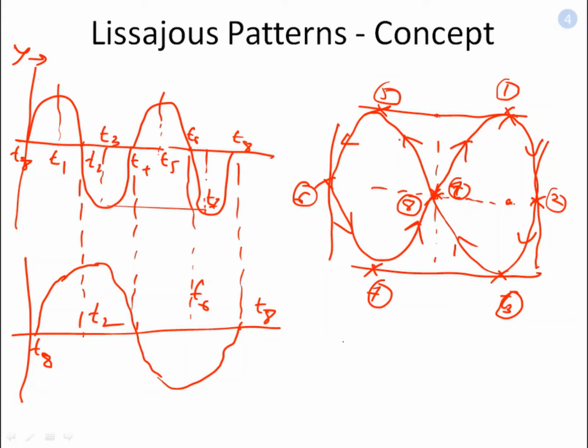So when we have to check the frequency Fy by Fx, Y plate is touched twice, while X plate is touched once. Either side, either you can take the top or bottom, or right or left, or you take the total number of touches. Y plate is touched 1, 2, 3, 4 times, X plate is touched 2 times, so 4 by 2 is 1, whichever way you like.